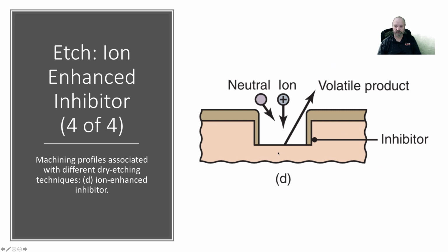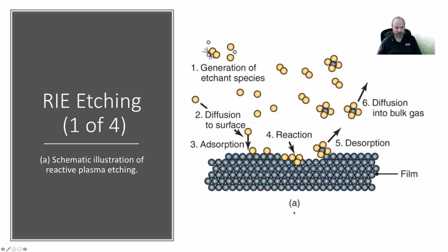Okay, so you etch a little bit, then you coat, you etch, you coat, and you switch back and forth between two different gas systems in your chamber, and you can slowly etch all the way down into the silicon. Sometimes they even etch all the way through the wafer with these sorts of processes. And again, this is the Bosch process, is based on the Bosch process.